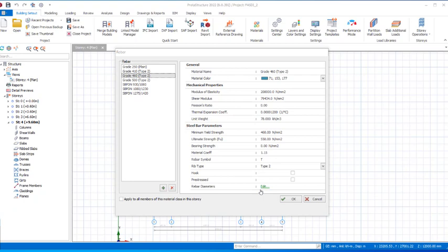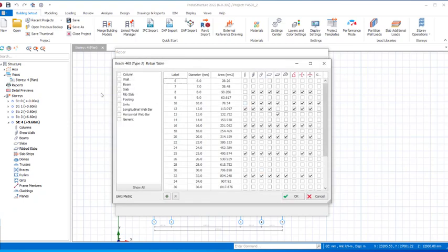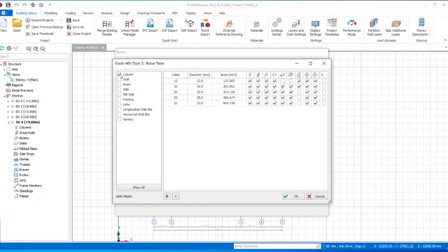For those particular bars, if you want to check the rebar diameter, you click on this edit provisions. In this edit provisions, you can now select the rebar diameter, the rebar that you want to consider. We are considering columns right there. In the columns, these are the available diameters for the columns. You can see the diameter levels as this.